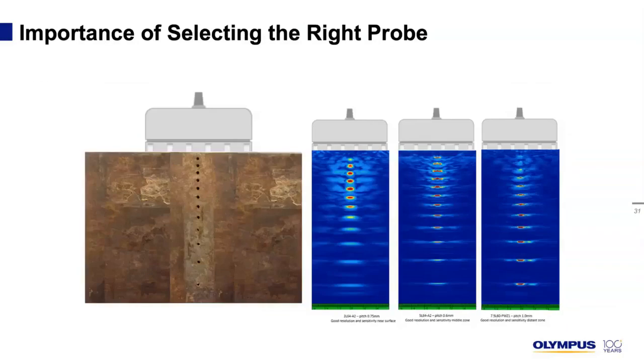Another important part of a proper scan plan or preparation is selecting the right probe. Same as with phase array, focusing has its limits, which means that what is true in phase array is also true in TFM. Probe frequency, element size, and number of elements in the probe are all factors that will have an impact on the setup and the quality of the inspection.